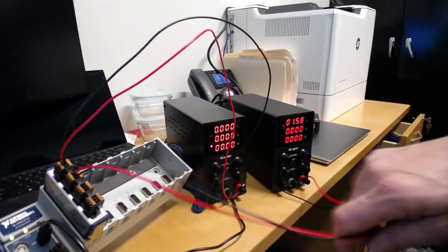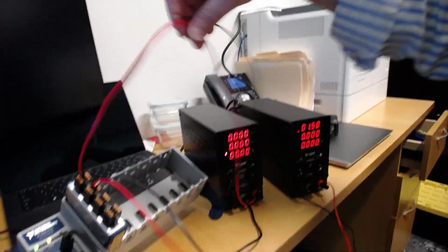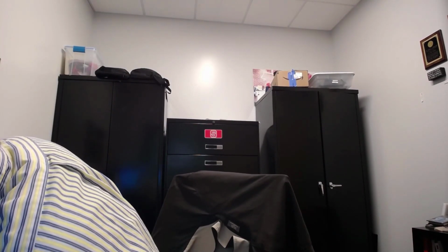See my wire right here? This is hooked to my right. This is hooked to my left, okay? So that's the naming. AI 0, how do I know that? Well, it says it on this module right here. Right here it says channel 0, channel 1, channel 2, channel 3. And that's the way all the NI modules work. They're 0, 1, 2, and 3. From an array standpoint, from MATLAB, as you'll learn, they're all 0 indexed.